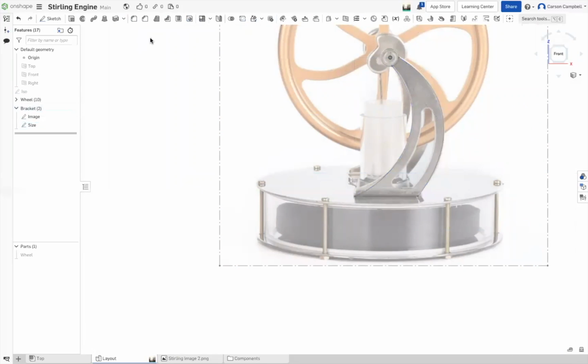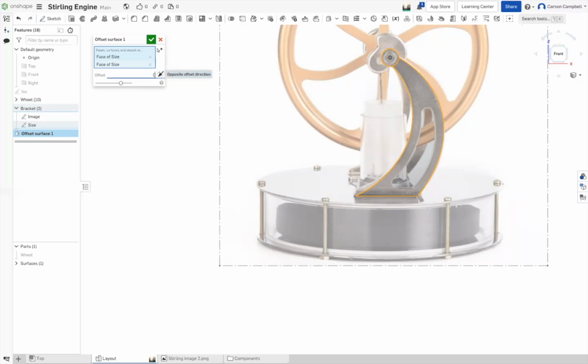All right. Now I want to create a face, a surface. So you need to go to your surfaces. Right, all the way. Keep going there. That's it. And that drop down box and fill. Well, there you go. And pick the islands. I don't know what islands are. So, okay, it's not fill. Cancel this. Yeah, it's an offset surface. Let's try that. And pick the island, pick the regions of the sketch. That one and the circle. Yeah. And say okay. Oh, change your offset to 0. And say okay.